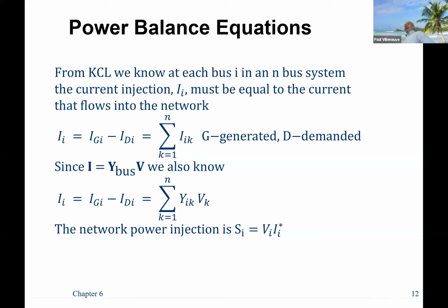difference of the two. Now, again, the current injected in there could be positive or negative, right? Just like with KCL, when we assume a direction of current, our injected current doesn't have to be necessarily positive going into a bus. It could be negative in that the current and the power is flowing out of the bus. Then we can go ahead and rewrite our equation as a bunch of the voltage differences multiplied by our Y bus. We did that already at the beginning of the semester.